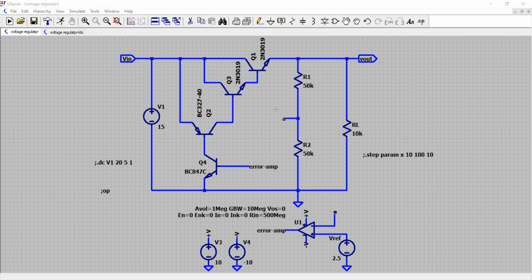And we got the equations, and we covered the fundamentals about how this circuit works. We also emphasized why it is called a standard regulator, and there we use this Darlington pair as a series pass transistor or power transistor that delivers the current to the load. And we then said, okay, this PNP transistor acts as a drive to this transistor, and this NPN transistor acts as a drive to this transistor.